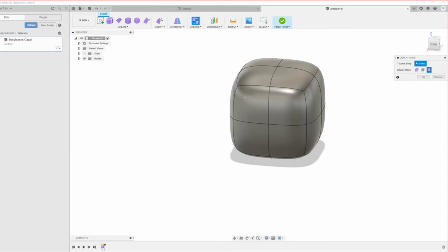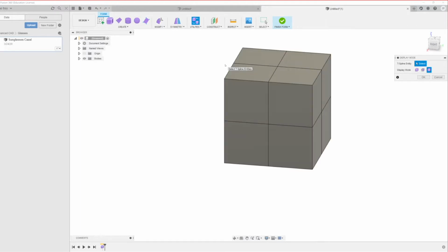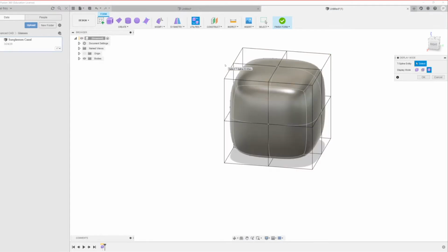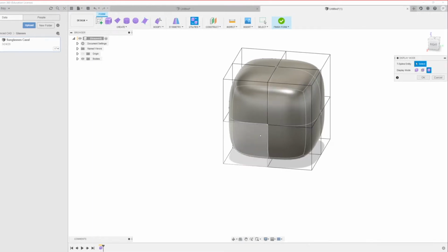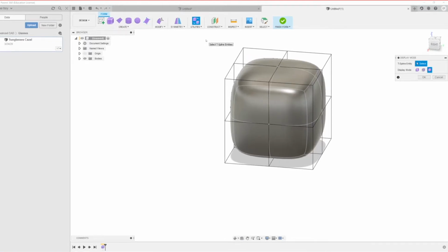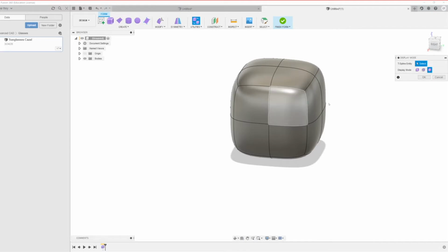The epitome of what freeform is, is that it actually understands this kind of geometry. Even if you go Alt 1 or Alt 2, 3, parameters also, your computer works with different kinds of geometry. When we get these faces, what the computer actually tries to do is blend them together. So it's called T-spline modeling. Instead of making a face that connects with a surface or an edge, it just tries to blend all these edges in nicely. As you can see here, the curvature is all really nice and smooth.